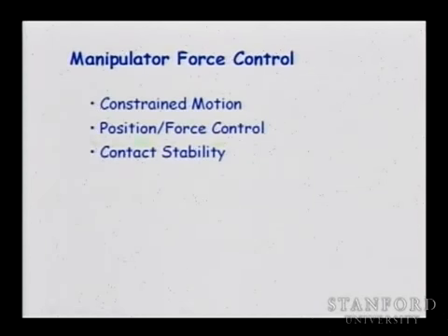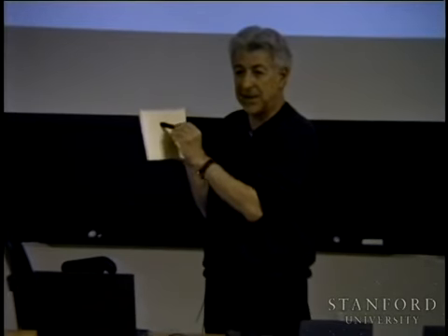Finally, we need to deal with the problem of controlling contact. Moving in free space is one thing, but moving in contact space is a different thing. Applying this force puts the whole structure under a constraint, and you have to account for these constraints and compute the normals, so as to find the reaction forces in order to control the forces being applied to the environment.